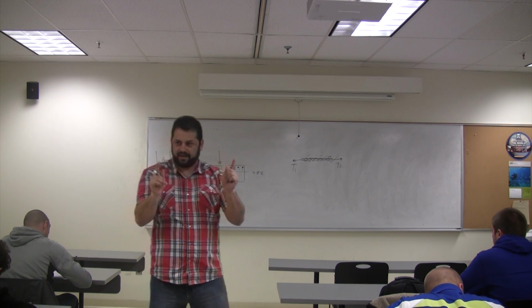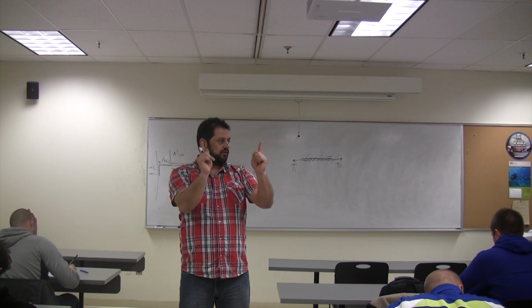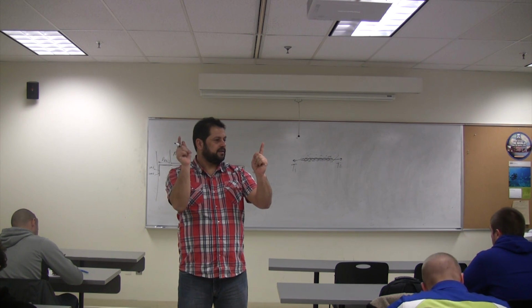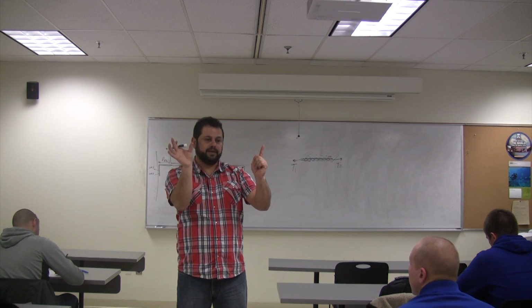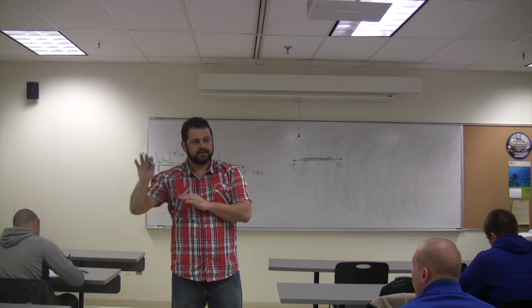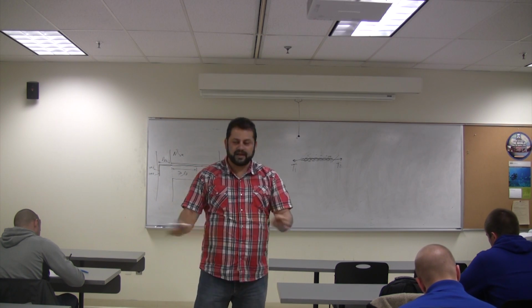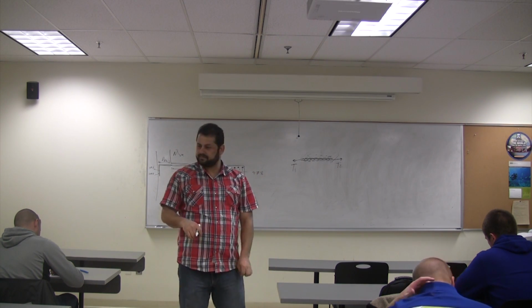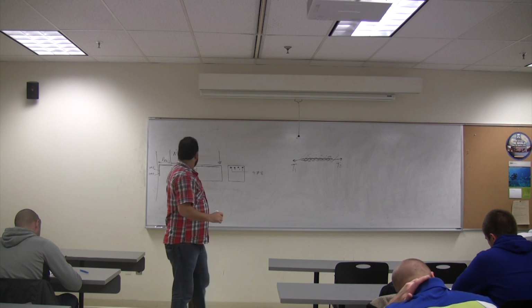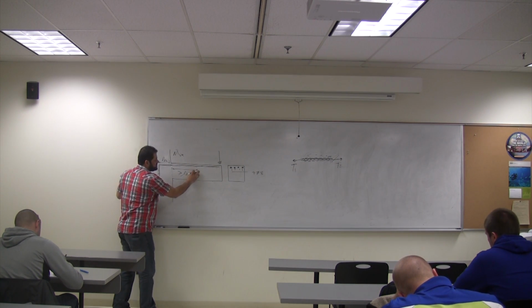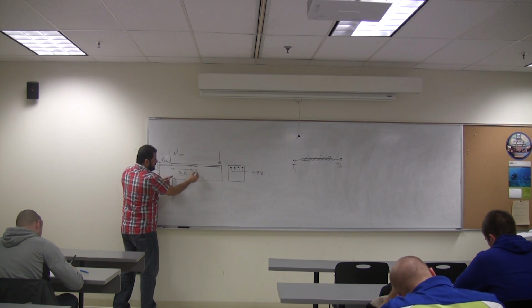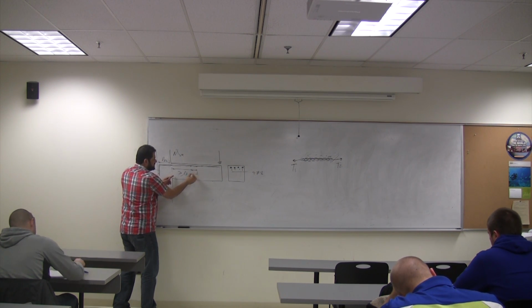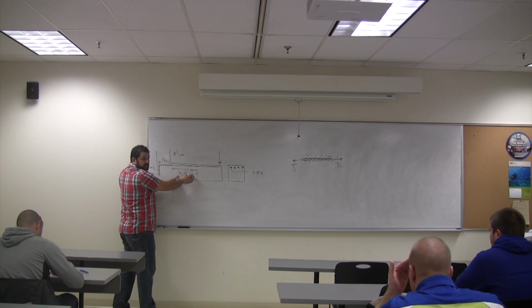Now they tell you this length, the theoretical cutoff length, plus the d or 12 db must be greater or equal to ld. If not, then you have to have ld. Good? So if this is my theoretical cutoff point, and this is d or 12 db, those lengths, both of those must be greater than ld.